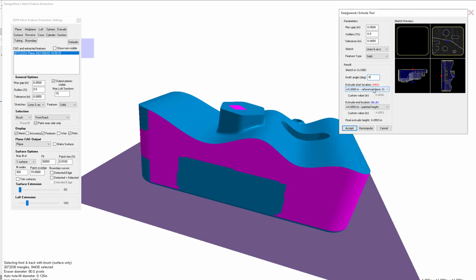They can do a feature, and if you've got fillets and chamfers on it, you've got to go back and edit the feature. So let's go ahead at this point. If you wanted to, there's two ways to do this. If you wanted to actually change other things in here, you would say recompute.